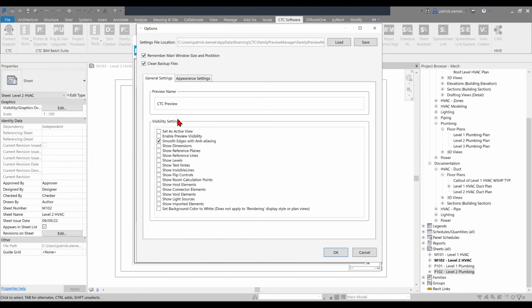So when it's going to create a view, as I mentioned, every time you save a family, a view is then selected to be saved. You could have that name, or you could have a view being created. If there is no view already with this name, it would just create a new one. So I could come here, say SolidCAD, and this could be the preview. That will be the name that's actually going to be created within that family. So it saves it to be kind of that little thumbnail image.